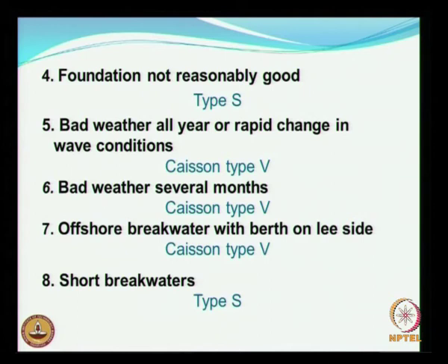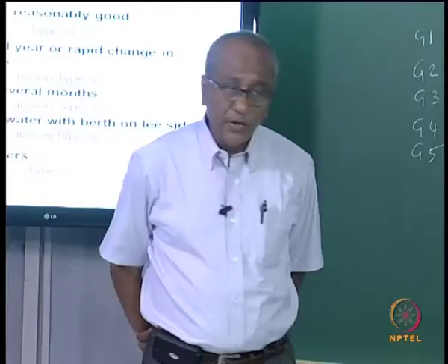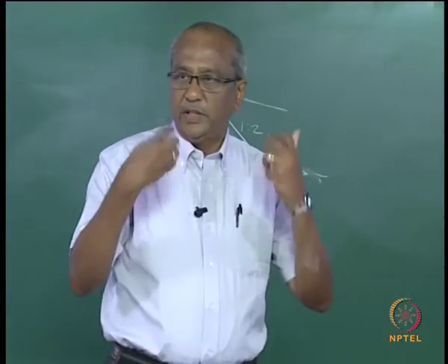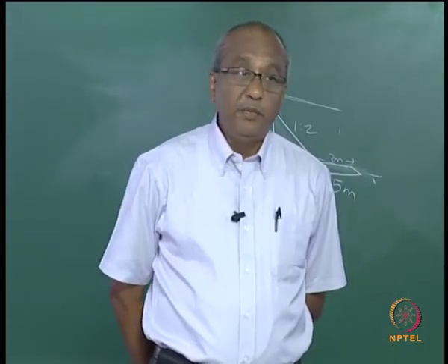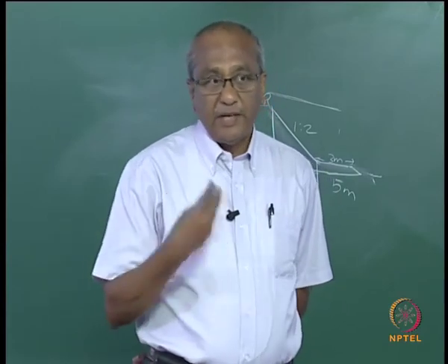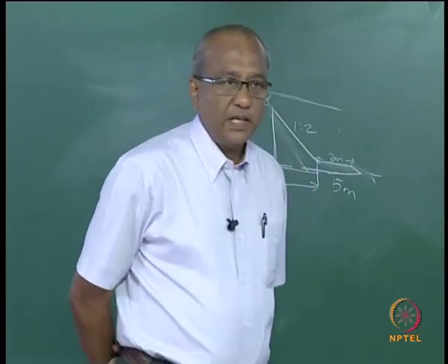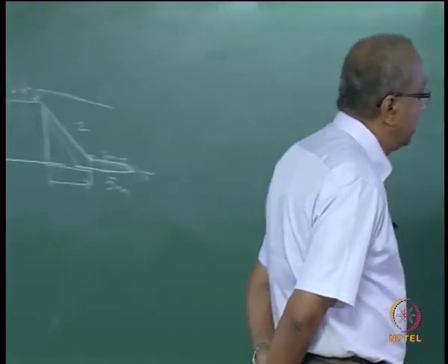Foundation not reasonably good, then it is better you go in for type S. If the seabed is, we have come across one area where you have some kind of loose sand under the seabed, and if you are forced to construct a breakwater under such environment, it is better to remove the entire material, although it is going to be very expensive, or have a special treatment to improve the strength of the soil and then start installing the breakwater.